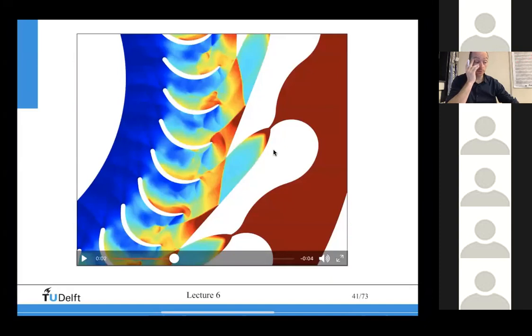So instead of boiling water, you boil an oil, and you get vapor. And that vapor is now expanded inside this turbine. That vapor is toluene vapor, and that is really operating for recovering waste heat.